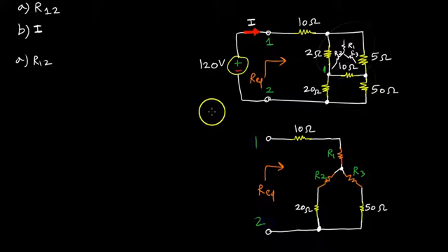Now, what I'm going to do is start looking for R1, and that is going to be whatever the product of 5 and 2 is, because as you can see here, if I bend this guy this way and bend this guy that way as they attach, these guys will be the adjacent resistors to the R1 resistor there. So that's going to be a 2 times a 5.